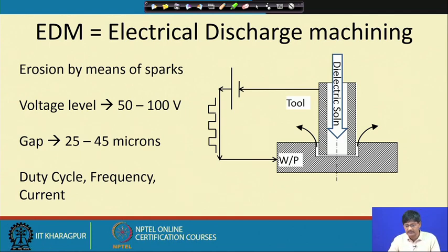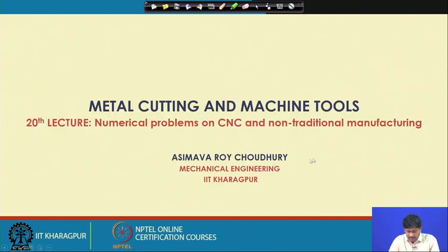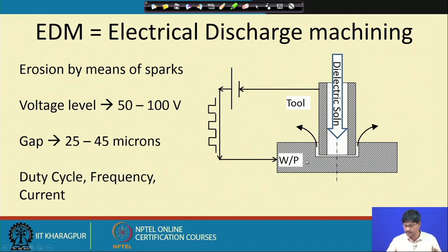Okay. Electrical discharge machining is almost the same, but the principle is completely different. The setup is almost the same. Here a dielectric fluid comes in and it creates in the gap which is created across this, sparks can jump through. So, if we have sparks jumping across this particular gap, it removes material, and ultimately when the tool is directed this way, these sparks remove sufficient material so that a conjugate profile of the tool is made on the workpiece.